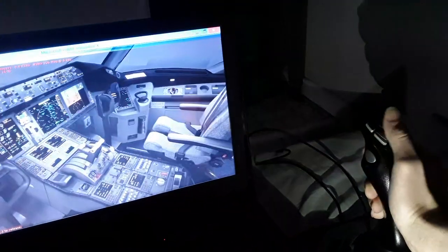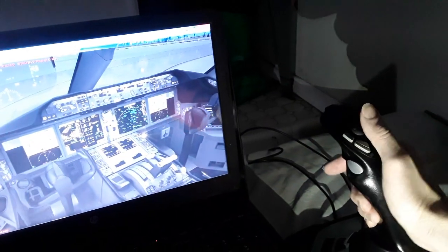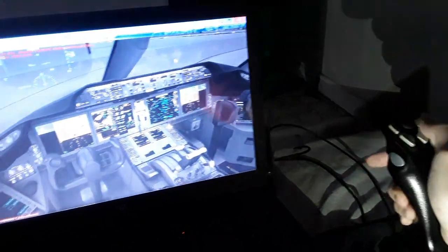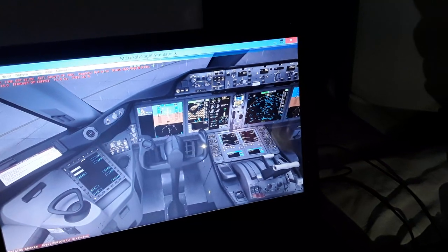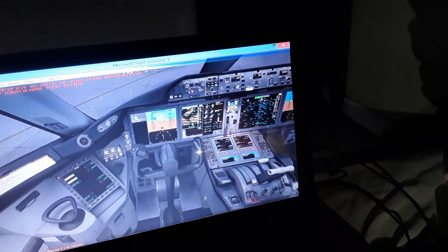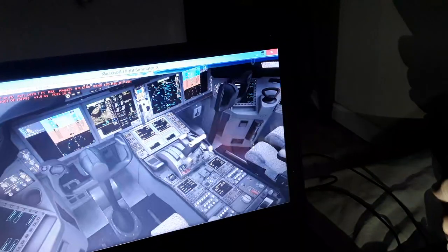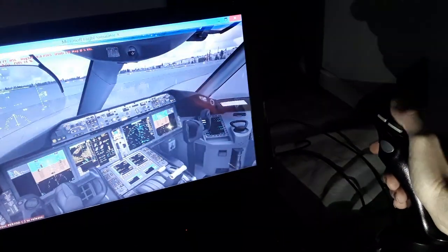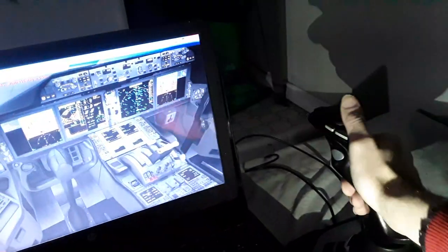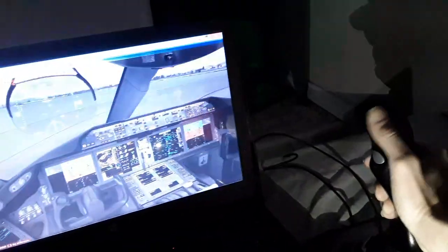Until some airspeed in takeoff, like in 70 knots, is deactivated. Then we have only the rudder function from the rudder pedals. So it has a deflection like 76 degrees when we are having low airspeed, like 10 knots, 30 knots. Then it's decreasing until maybe 7 degrees from above 40 knots in takeoff, until 0 at 70, maybe 80 knots. So you can see here we can climb, descend, make turns in flight, use all the flight controls, nose steering in the ground over here.